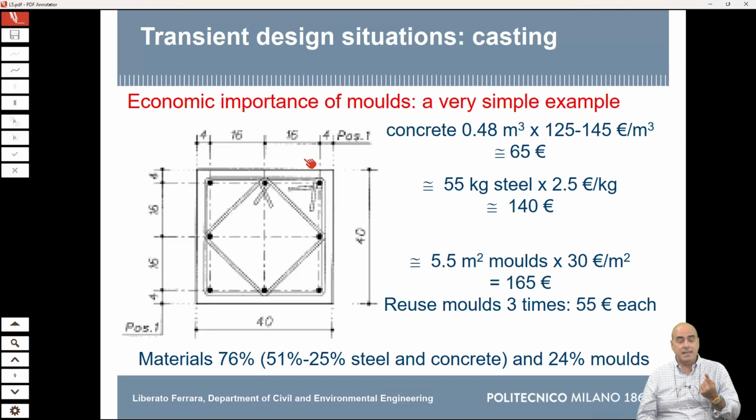The other thing is that if you vibrate the concrete, and generally you vibrate the concrete in columns going from the top, or you vibrate at the mold, your timber molds tend to deform. So you will have columns, you risk to have columns which at a certain point they bulge a little bit and so on.